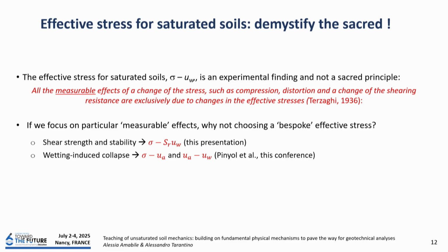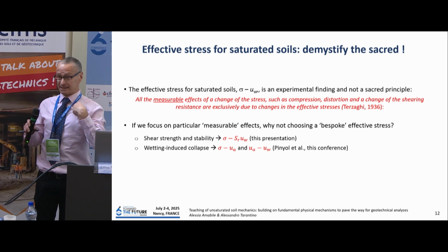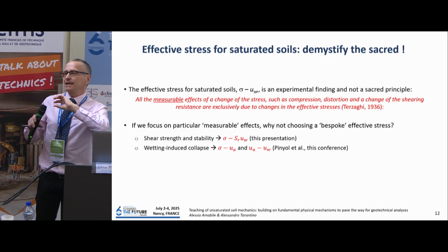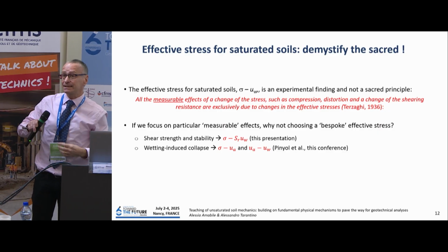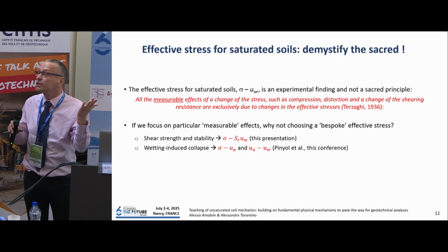Is that terrible? No, because even in the saturated soil, you have cases where the effective stress that we use does not work. For example, if the stiffness of the matrix is comparable with the stiffness of the grain, our effective stress is not working, so there's nothing new here.